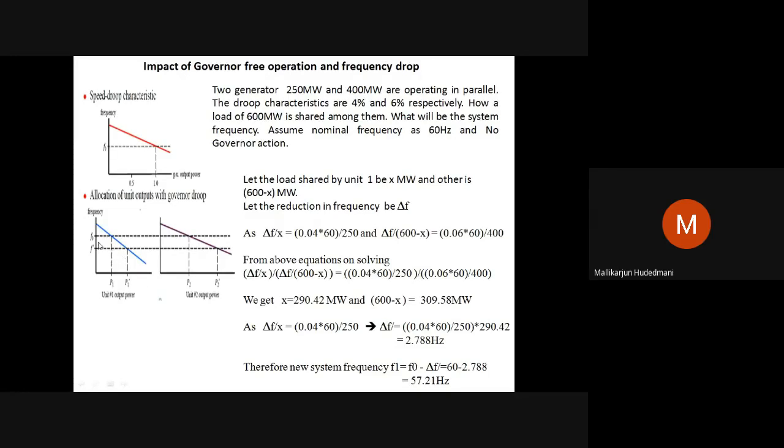Let us say initially they were at frequency f0, when you connect them to one another. Base frequency somewhere f0. This is intersecting this blue line somewhere here. Power output available at that time was say P1 megawatt from machine number 1. And similarly the f0 line intersecting on this curve, projected downward, shows you P2.